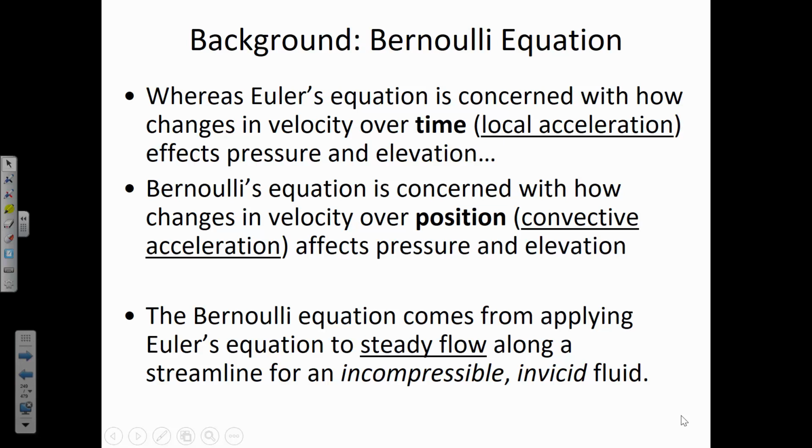So that's kind of why it's okay to apply Bernoulli's equation to fluids like water, is that when we do apply it, we're not going to apply it over the course of miles. We're going to apply it over the course of maybe a few centimeters. And in the lab, we'll apply Bernoulli's equation, and we'll have fairly good luck with it. We'll send water through a contracting section. We're going to measure the pressure change. And what we actually observe in the lab pretty accurately conforms to what Bernoulli's equation will predict.